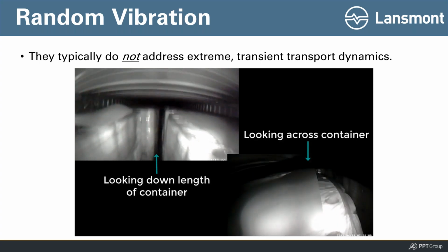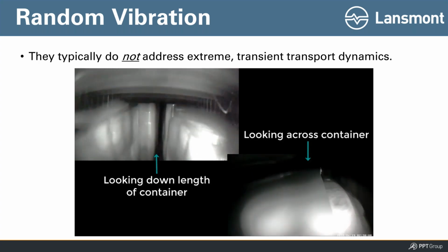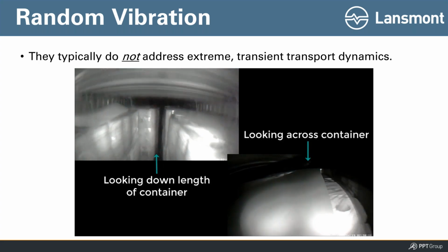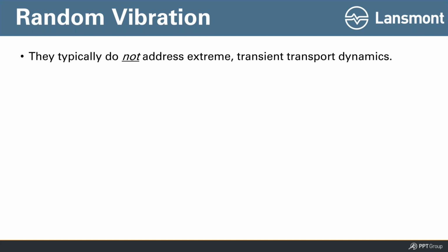Big input happens. Those loads actually jump so high, quite frankly, from that rough road, that they hit the top of the container. And is that vibration? Do we mix that into our vibration test? Would we like to mix it into our vibration test? Maybe, but we don't. I would say 99.9% of the vibration tests that people perform doing random vibration, ISTA, ASTM, MIL standard, ISO testing, that's not part of or included in the approach to those random vibration profiles.